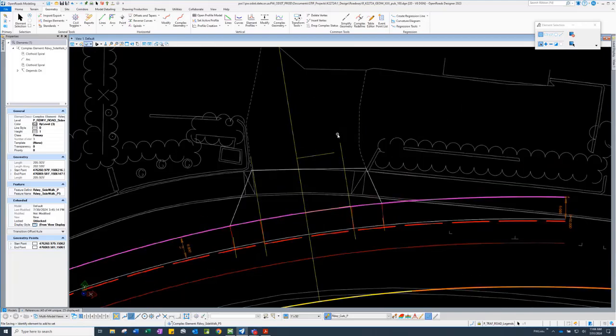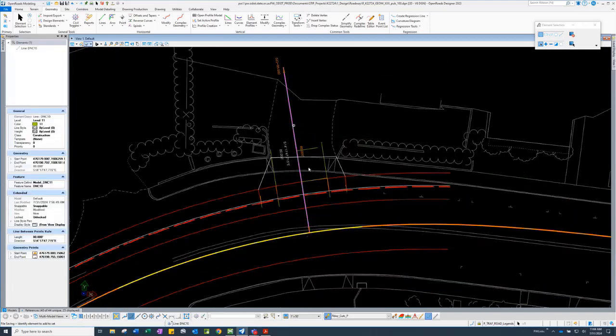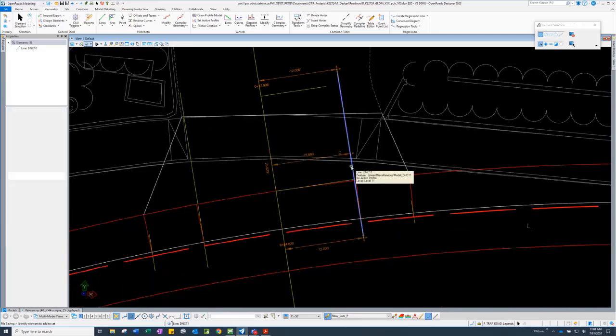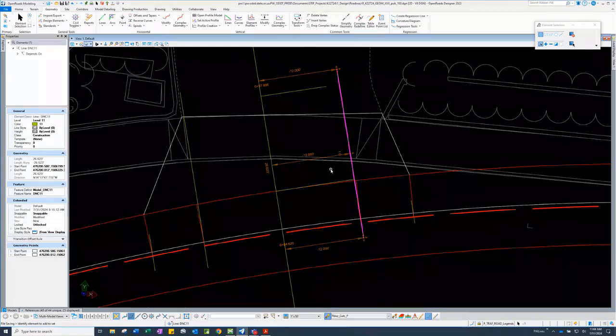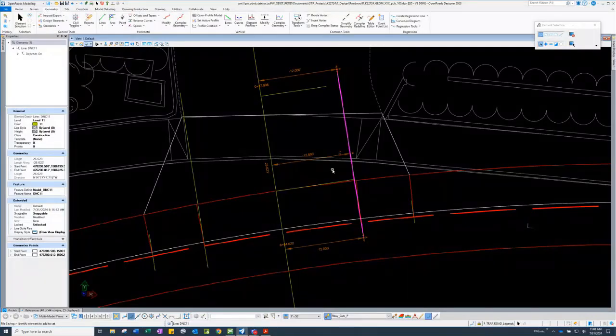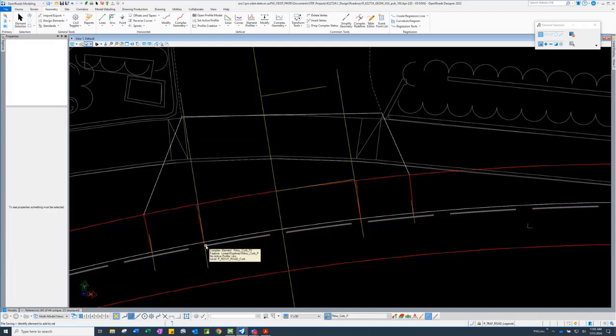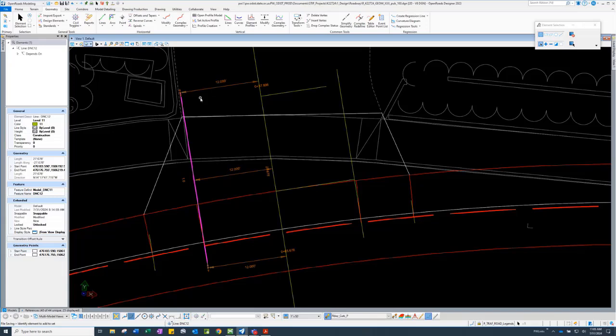So in this scenario, I have the center line of the driveway roughly placed here. I have done a partial offset of 12 feet because this is a 24-foot wide driveway. Per the access agreement, it was agreed to do 24 feet. When it's on a curve, the 24 feet is measured at the point of gutter in a curved scenario, or at least that was the discussion with our access management folks. And so I used the partial offset to show where that would line up.